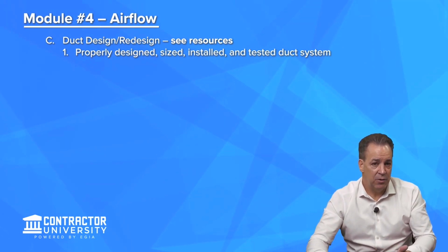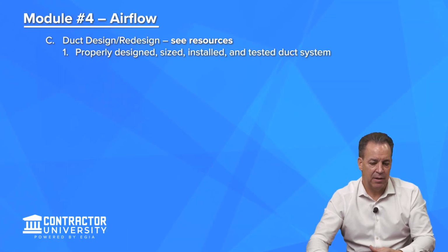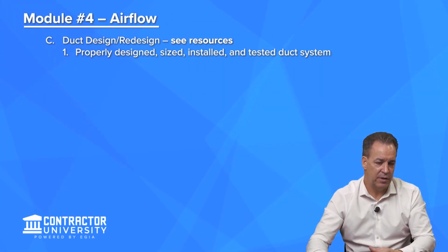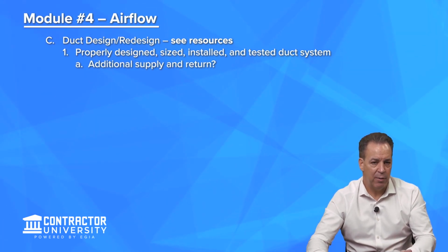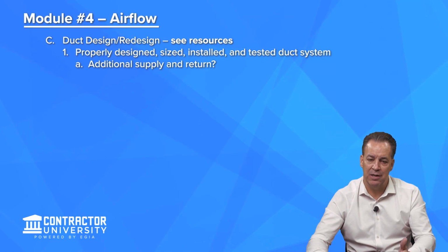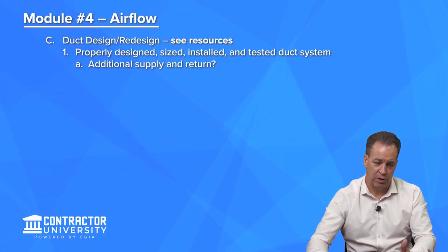And if your company isn't doing that, I highly suggest that the company get indoctrinated into National Comfort Institute protocols. Additional returns, supplies and returns, are they required? More often than not, an additional return is going to be required, or enlarging a return.